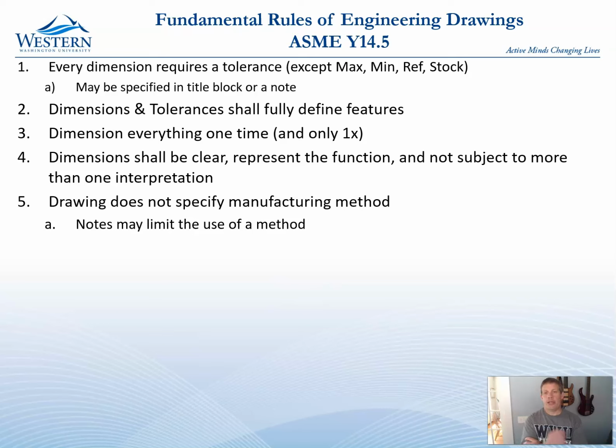What you do is you say what the diameter of the hole is, and if you have a tight tolerance on it, then the manufacturer will understand that it needs to be reamed to get that tolerance. Or if it has a tight cylindricity, or if it has some sort of smoothness on the inside of the bore, some call out for something like that, surface finish or something, then they would understand that it needs to be reamed. But you don't tell them how to do it.